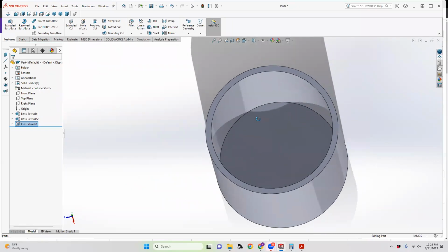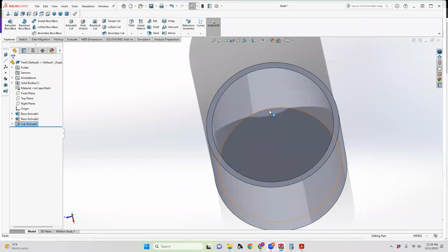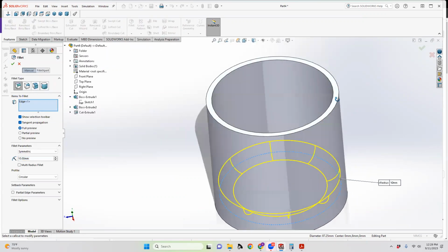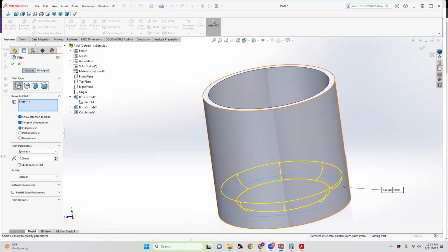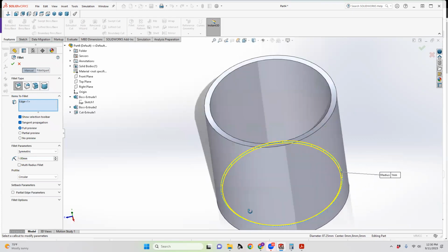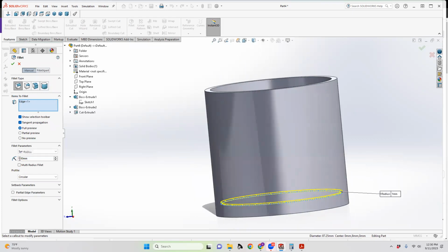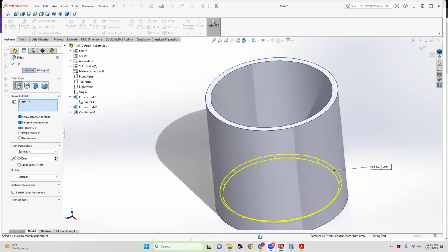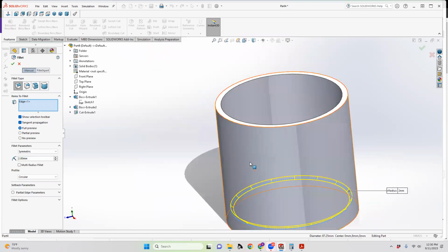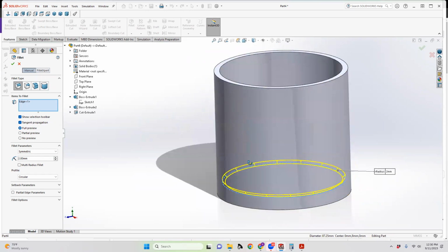Then on the inside, since they're never square, what we're going to do is called a fillet. So there's two options. There's a fillet, which is rounded, and a chamfer. We're going to do a fillet. It's going to show you a preview with a 10 millimeter radius. Nope, not even close. But typically somewhere around 1 millimeter radius is a little bit more accurate. Some mugs might be closer to about 2, but that's about your limit for the fillet. So you're going to see this technique also used in that tutorial. So this is where to practically use that. So maybe that's about right.